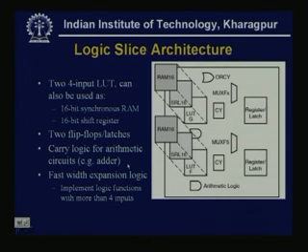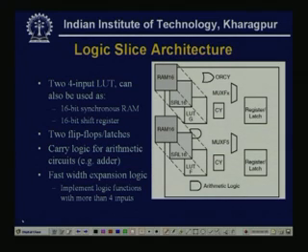Now, this is another type of architecture we call the logic slice architecture. Again, this is a real life example. See here, two 4 input LUTs can also be used. This is a complex thing. So far we have seen only one lookup table. Now, here two 4 input LUTs can also be used as 16-bit synchronous RAM and 16-bit shift registers.